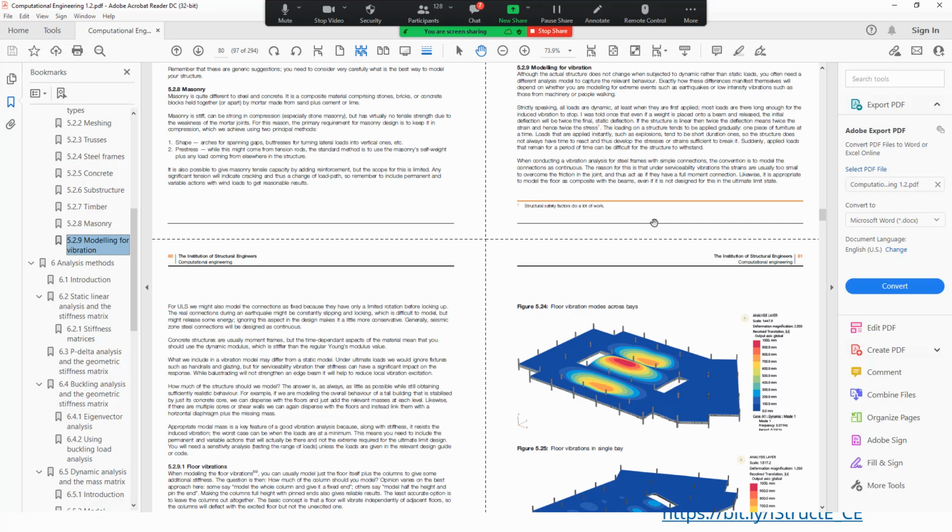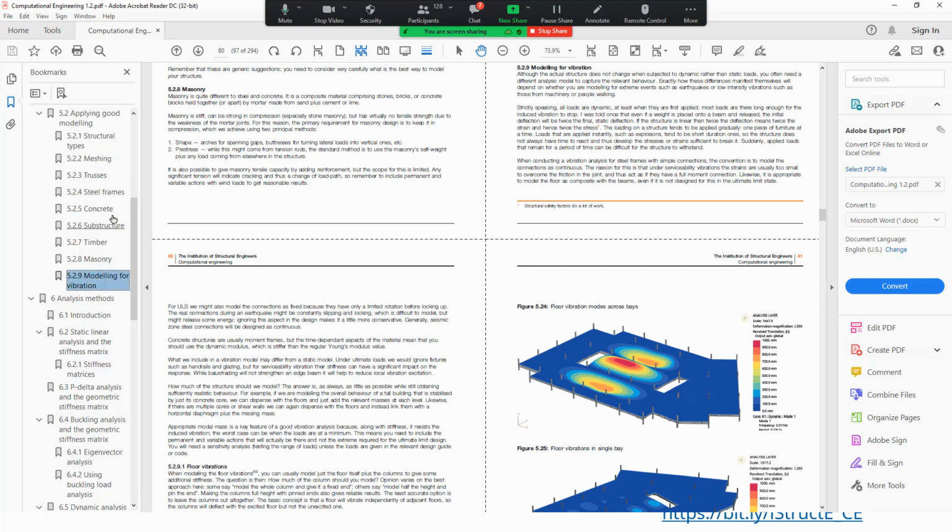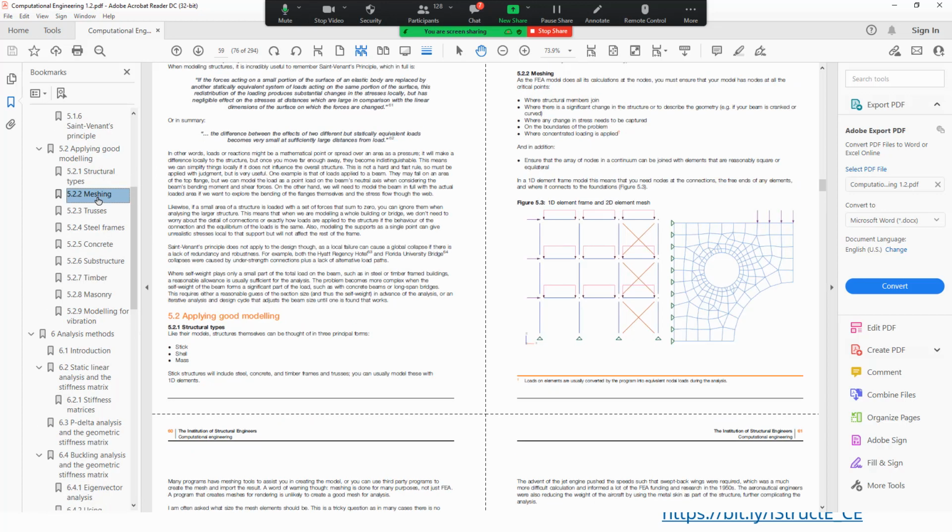Great. And then the next question: when deciding on the mesh size for an RC slab in an FE analysis, what factors must one consider? Which is also in here somewhere, possibly under the meshing section. Mesh size: first of all, there is a minimum mesh size, and the rule of thumb for the minimum mesh size is twice the thickness. Below that, you're getting into deep beam theory and the analogies break down. With a larger mesh size, if you make the mesh too big, the results are too crude. So generally, you're looking at breaking the spans down into about 10 elements to get good beam moments in a mesh. Ironically, if you've got a span to depth ratio of 20, then 10 elements versus twice the element thickness actually gives you the same dimension.